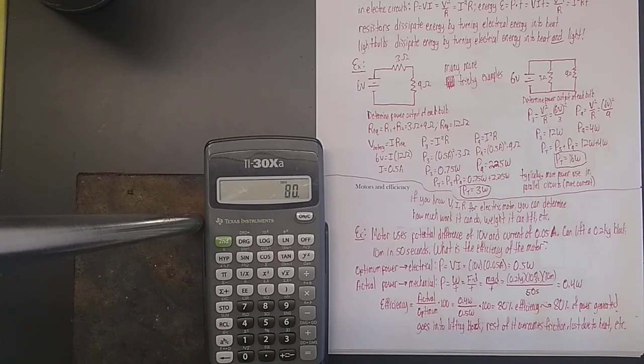So the fact that this is not operating at 100% efficiency isn't necessarily bad. It's inevitable. Because this motor has moving parts, you're never going to have a perfectly frictionless situation. You're going to have some things that rub against each other. That energy that's lost because of that needs to be overcome. As these things move, they get hot because of that friction, and that energy lost to heat needs to be overcome. So that's why the efficiency won't be 100%. But that's a neat way to relate our study of electrical power and energy to mechanical power and energy, and a quick look at efficiency.